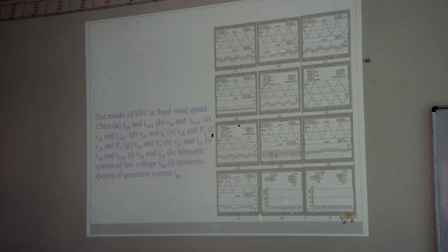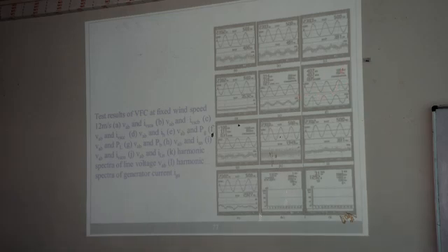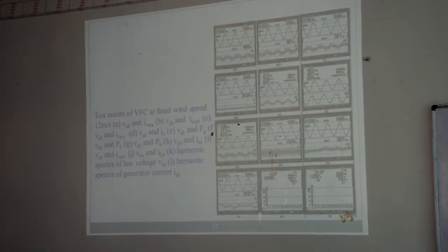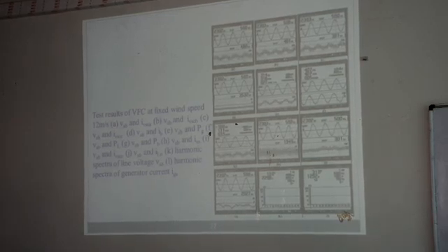These are your DSC currents. This is your compensating current for neutral because the load is not balanced perfectly. And this is the power generation through your generator. This is the load demand. So here the power generation is 3.14 kilowatt, but the demand is more, 4.017 kilowatt. So the difference amount of this power is supplied by your storage, which is at the DC link of your 4-leg DSC.